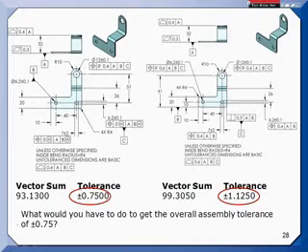The way Rich and I have kind of batted this back and forth over the years, the way I've always looked at parts like this is that the 6.2 hole you have there is a datum feature which is used to identify datum B. And datum B is always going to be absolutely perfectly perpendicular to A, the datum itself, right?